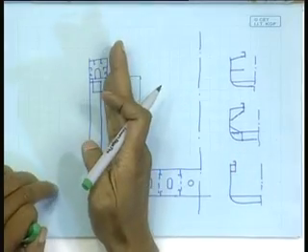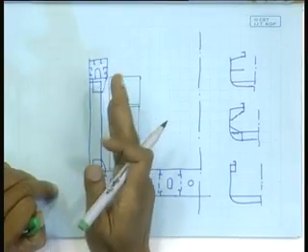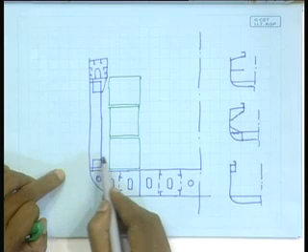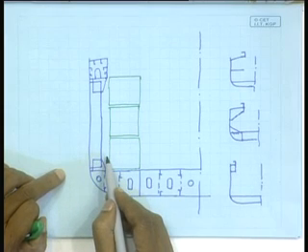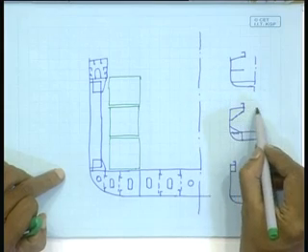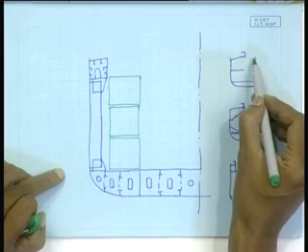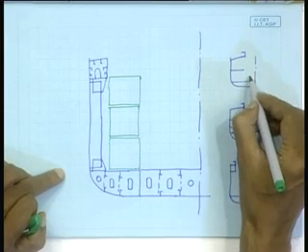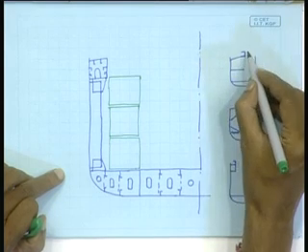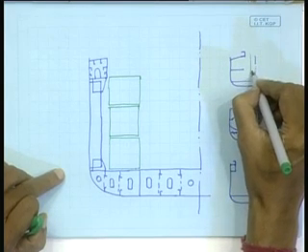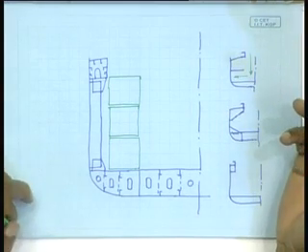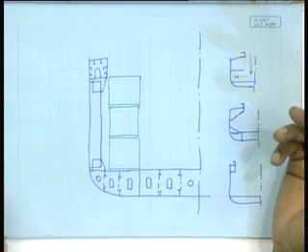So, I will have to have the hatch opening as big as possible, such that I do not waste any space in the side, right, because if I have a small opening like this in case of a bulk carrier or general cargo ship, then I have to lower the container and shift it laterally, which is definitely not a worthwhile proposition, right.